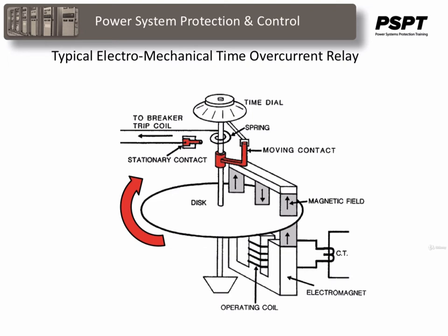Now we are talking about secondary amps here, coming out of a current transformer which is connected to the line. The time dial usually has positions marked from 0 to 10, where at 0 the contact is permanently closed and 10 is the largest distance it has to travel.